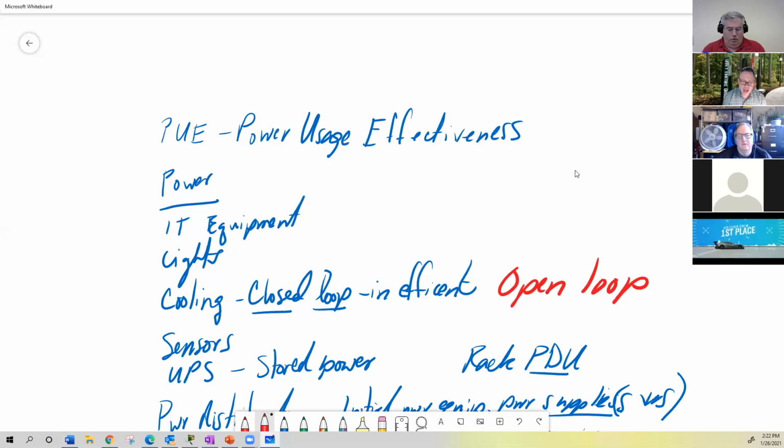Because there's a wide range, it allows flexibility in how you cool your data center. They call some of them high temp data centers. Okay. And so they've said, well, why do we spend so much money cooling our air to 67 degrees? Why don't we just cool it to 80? Well, that introduces other elements, because the second that you have a failure in your cooling, in a matter of 5 or 10 minutes, you're over 100 degrees. So you've got to be very careful.